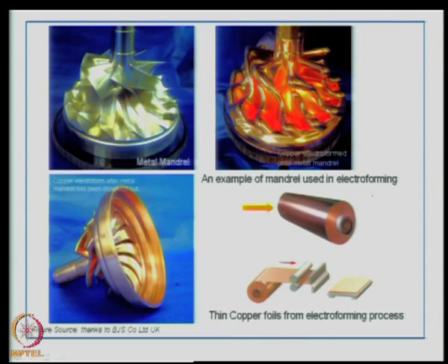If you are going to mill every part like this, it is going to take a lot of time. So, the best solution is electroforming. So, if you make a mandrel for a structure which finally should be this, okay, this is a mold-like structure you make out of aluminum, for example, in this case, which this company has done.